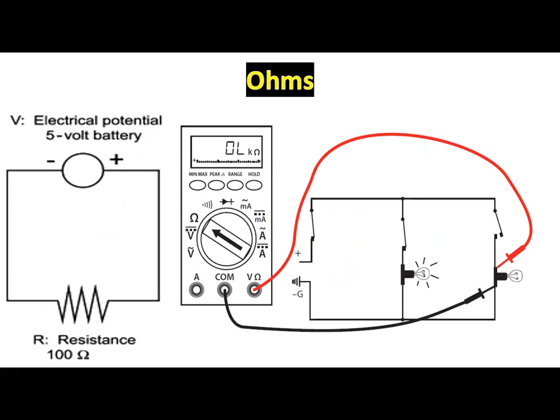Electrical resistance may be considered the opposition to electron movement in a circuit, and this resistance is measured in ohms. The size, length, type, and temperature of a conductor determine its resistance. For example, a smaller diameter wire has a higher resistance to electron movement compared to a large diameter wire. Material is another significant contributor to resistance, both positively and adversely.